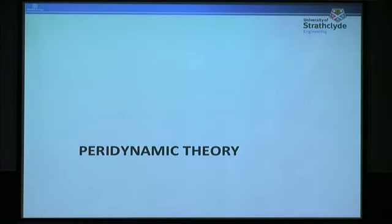So if you use several physics laws, including global balance of linear momentum, then we can obtain our equation of motion. And to obtain our equation of motion, what he basically did is he expressed the traction vector in terms of something that he introduced as the stress tensor. So now we have an equation of motion. If we can solve this equation of motion, we can find out the motion of each material point, and it will give us all the information that we need.